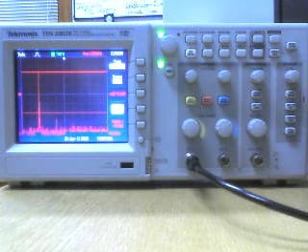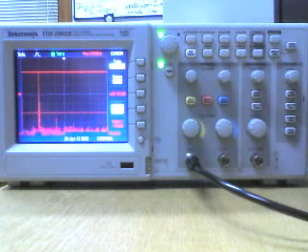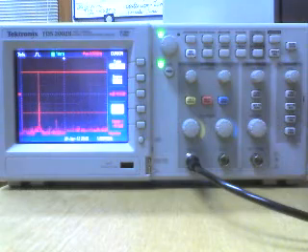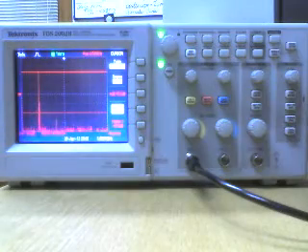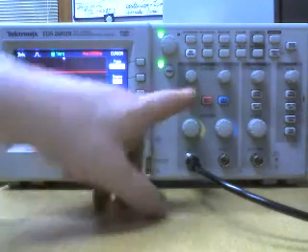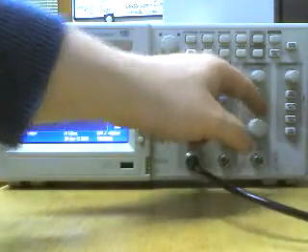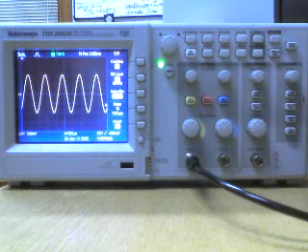Just for your reference, 0 dB equals what? 1 volt. Just remember that, and then you can do your conversion. See if you can do the conversion. At the moment it's minus 3.39 dBs, and you want to get to the signal. If we go back to channel 1 and reset this so you can see some cycles, 2 volts is equal to 2 volts peak to peak. Job done. And that's the oscilloscope.